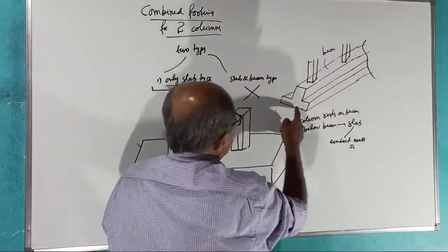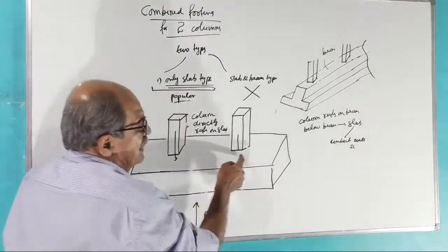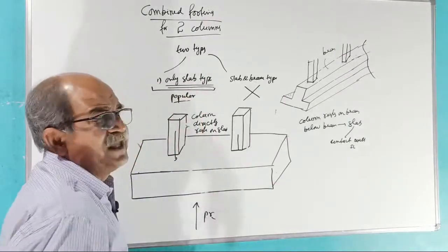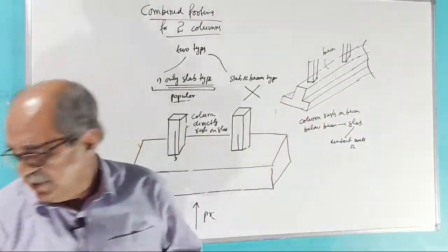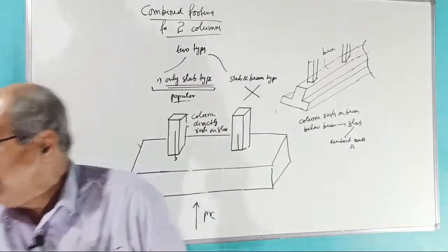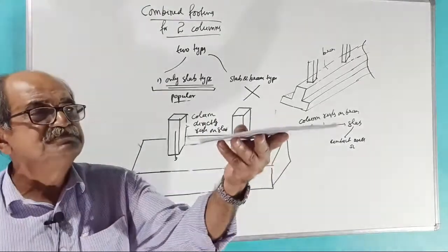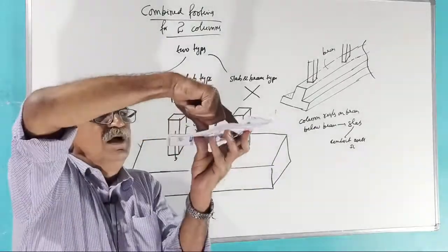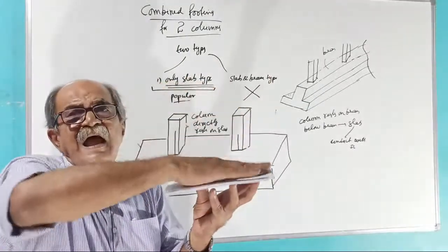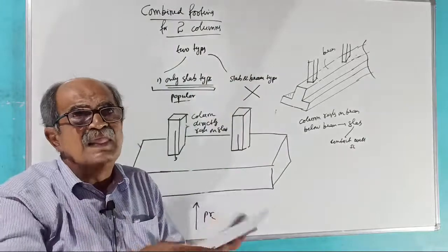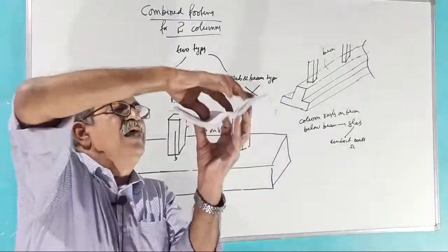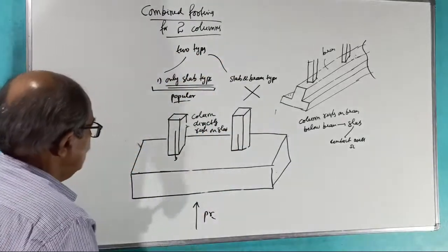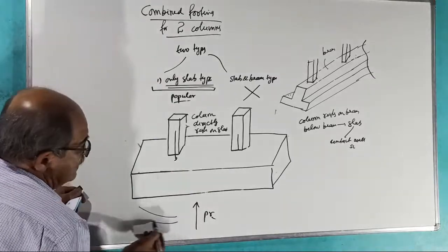Now, here what will happen is, the slab will undergo lengthwise bending and also widthwise bending. Anybody can tell? Lengthwise bending, fully. See, understand correctly, I will not hurry. This is the slab, my two fingers are the columns. Pressure is coming here. It will undergo lengthwise bending and widthwise bending. Lengthwise bending is for the entire length. How will it bend? Usually it will sag here.